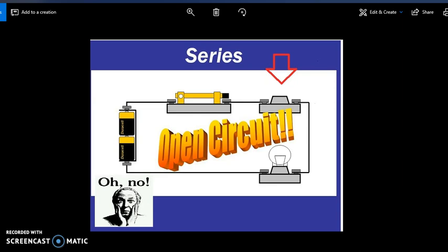The next question was, if the 80 ohm resistor gave out on us, would the circuit continue? My answer is no. It wouldn't, because it's a series circuit. If you remove a resistor from there, the circuit's shot. It's one path, like Crane said, one path for the current to flow.